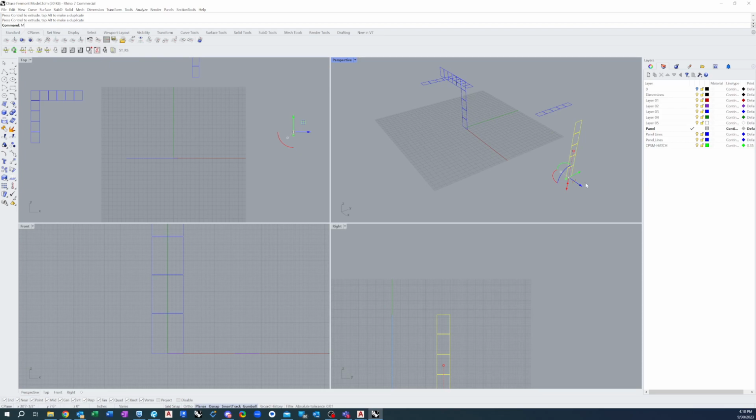So move, MO, from here to here. Hopefully I laid everything out right in CAD. These joints line up. So one thing you can do is hit your zoom command and just highlight your window, and it'll help for your zooming in.